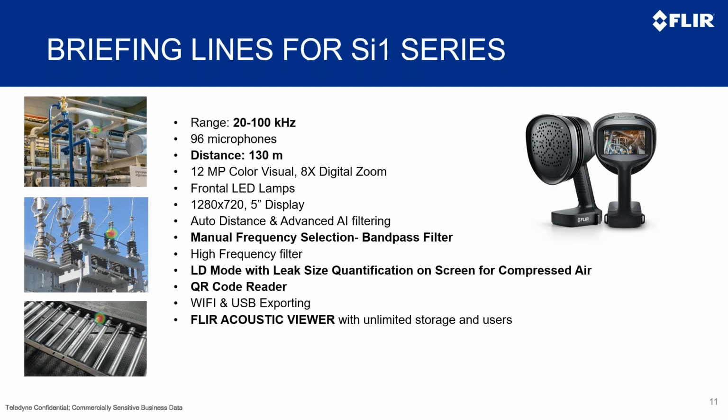We have LD mode, basically a one-mode camera with leak size quantification on the screen for compressed air. So we will give the quantification of the leak size for compressed air only, but we find any kind of pressurized gas leak. The only thing is that we don't give the quantification of the leak size. So for leak finding, it's a perfect camera as well. We have QR code reading, Wi-Fi and USB exporting. And we, of course, have at your disposal the FLIR Acoustic Viewer, as we do for all of our acoustic cameras.